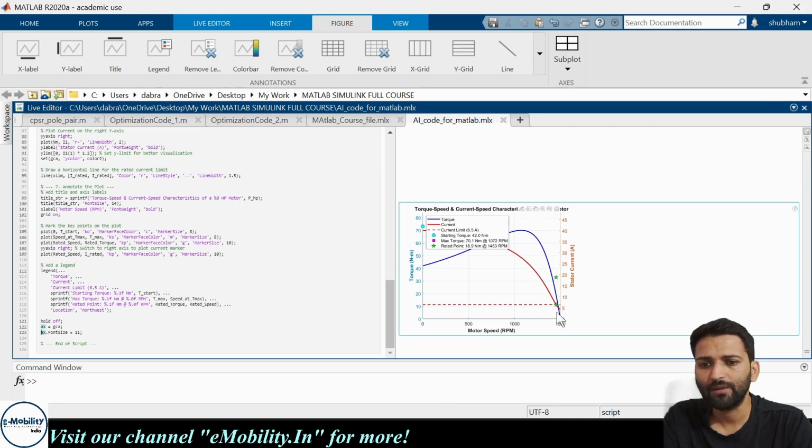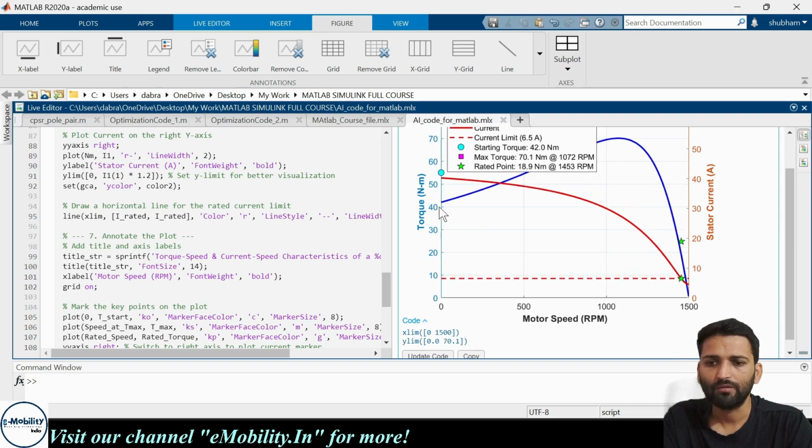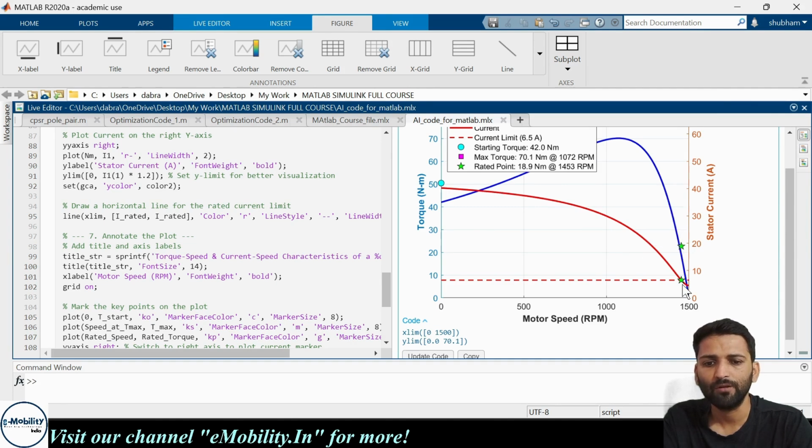The current limit has been shown here. If I zoom in, yes, the current limit is 6.5 ampere. Starting torque is 42 Newton meter, maximum torque is 70 Newton meter, and the rated point is around 18.9. So it has a very good starting torque. This green star is showing the rated point, and this is showing our point at the current limit.